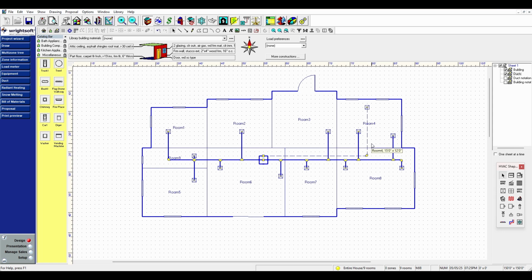The HVAC system is constantly recirculating the air. It's not always pulling in air from outside. It would have to work too hard. Instead, it sucks in the air that's already inside the house, sends that back to the coil system to cool it down or heat it up, depending on whether you're running cooling or heating, and then sends it back out through the supply ducts back throughout the house. Okay, I'm going to put in another return grill.